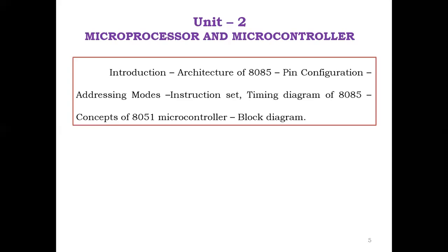At the same time we can use MOV and ADD, but which one is best can be determined by the timing diagram. That is, the total number of T states required to execute is what we are going to calculate in the timing diagram of 8085. Let's see one by one.